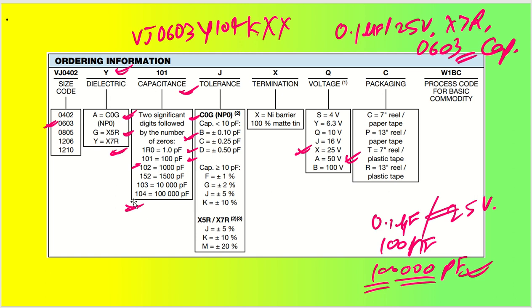However, this is not a recommended method to find the part number of a capacitor based on your requirement. You can directly go to one of the distributor websites, and there you can filter all the values and specifications you want, and based on that it will give you several part numbers based on availability and tolerance. You can find some of them directly. Now, what other parameters do we have to keep in mind? We have already understood the package.